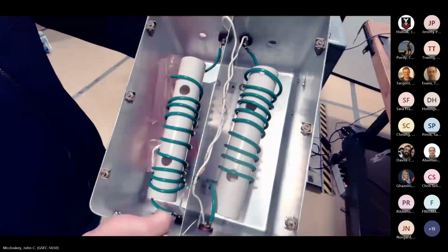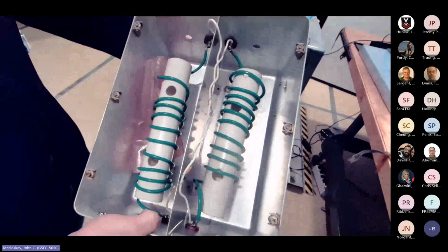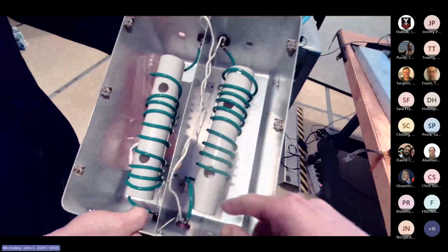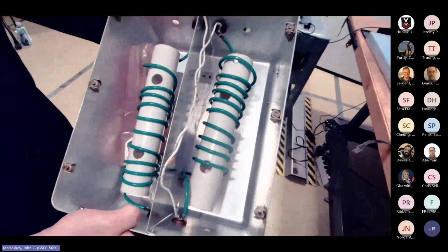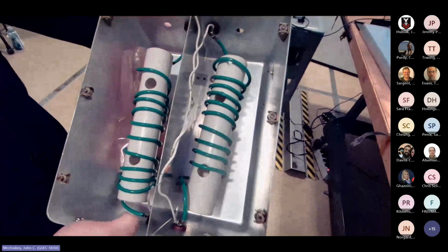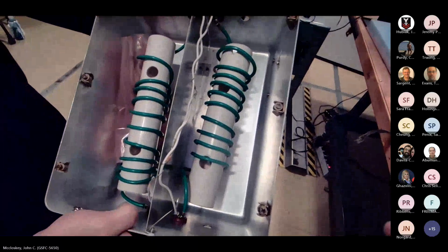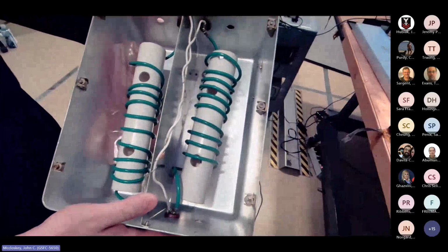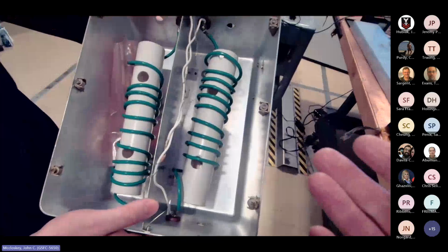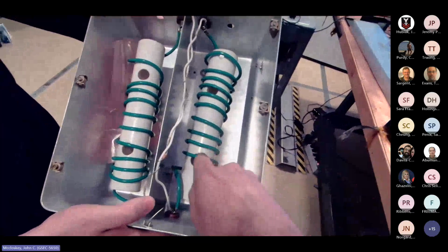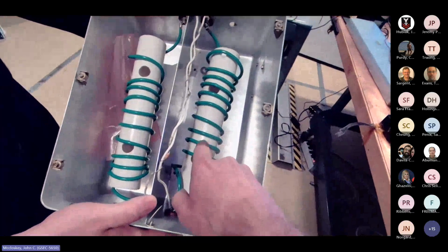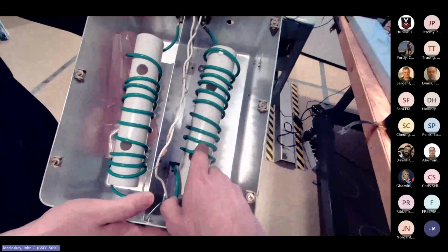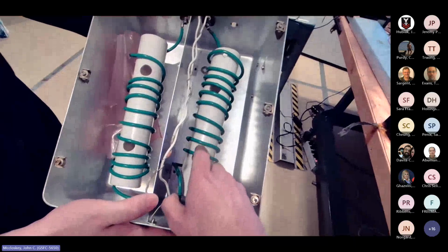In theory, you can calculate based on the diameter of your coil and how many turns and all that sort of stuff. The math for all that is pretty straightforward for low frequencies. So it's not too hard to get a 2 microhenry inductor to work up to maybe a couple megahertz, maybe up to 10 megahertz or so. But at higher frequencies, what do you have here? Of course it's successive windings of our coil, but what does the hidden schematic tell you is between these two things?